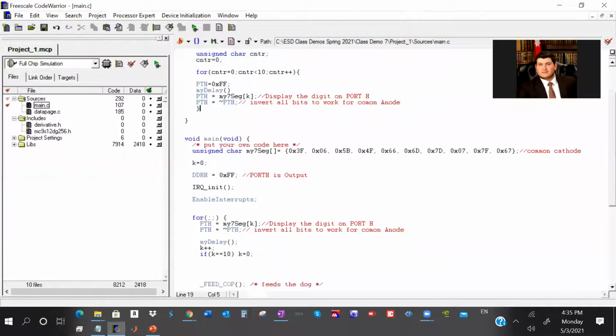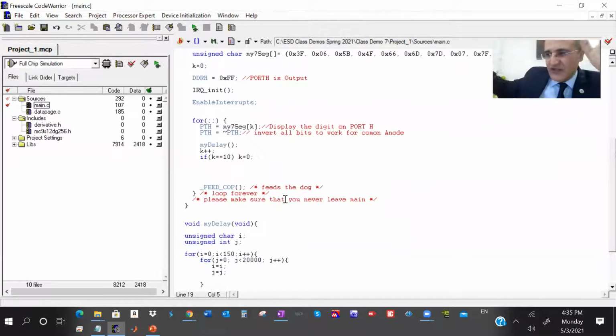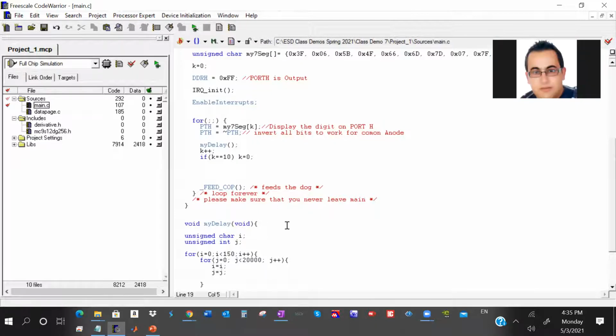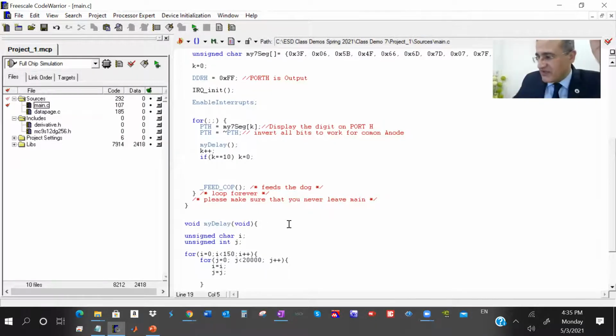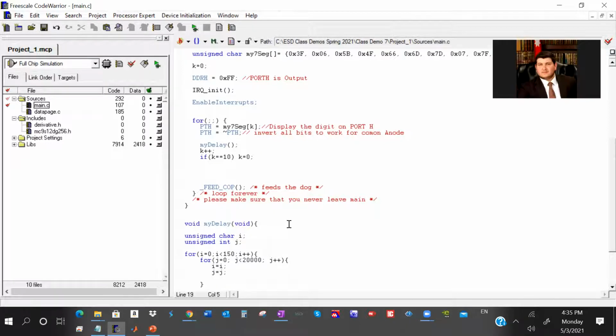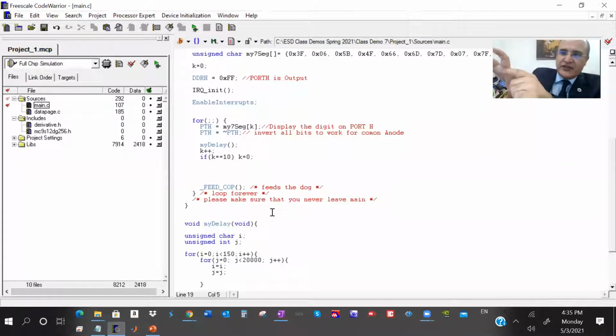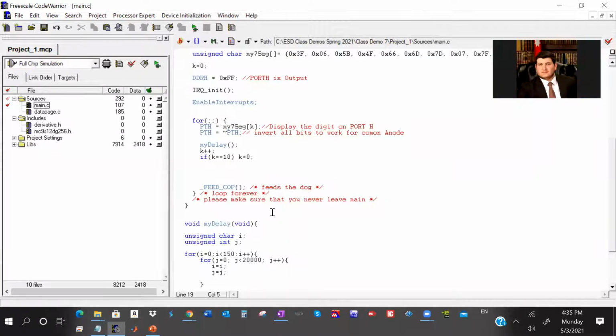Tamam. Pretend it's something external outside. I can just take port E and connect it to ground and remove it instead of the button. Doctor, so you want to connect an external push button, for example? Yeah, push button. But here I really am going to use this one, but I'm not going to read it through port M. I'm just going to use the wire. I'm going to connect it externally, from port E1 to port M6.